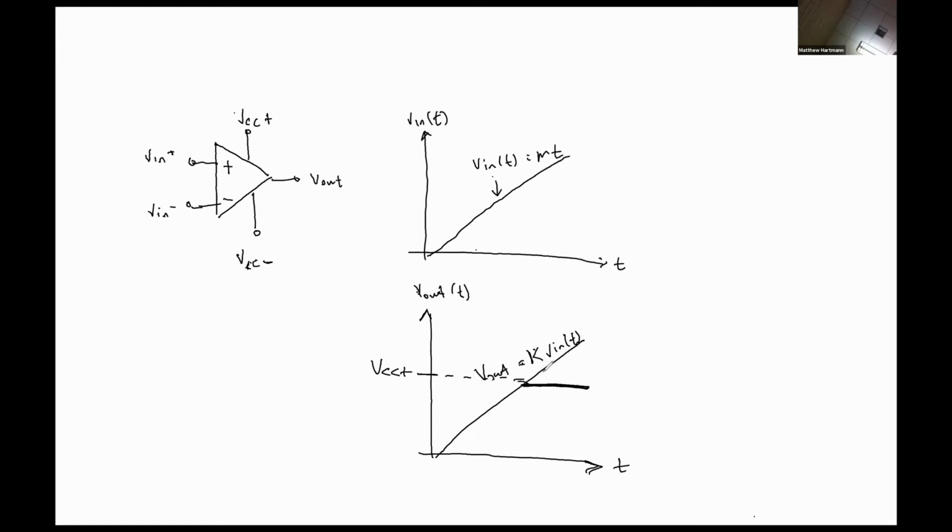It doesn't continue to increase up here, it just stays flat like this. So we're actually clipping off our input signal. The hysteresis portion comes from the fact that it's going to stay there even as we decrease the voltage until we go below this threshold. We could see a similar effect if we tried to get more negative than the negative power supply voltage.